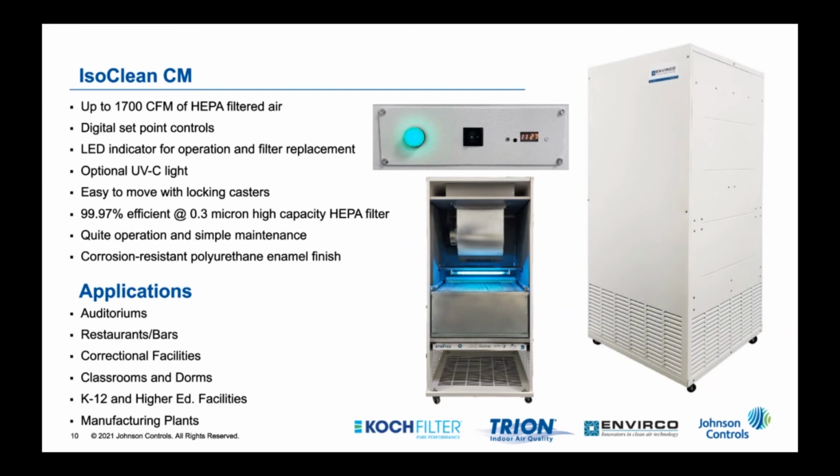Now this photograph is showing the front off with the UV light on, and I want to stress that that is an absolute no-go. It was only done for photographic effect here. Anytime you're working on this unit, you want to make sure that it's turned off and unplugged, because the UV light can be damaging to your eyesight. As for applications, you can see most of these are larger type spaces, auditoriums, restaurants. These units are going into a lot of classrooms.